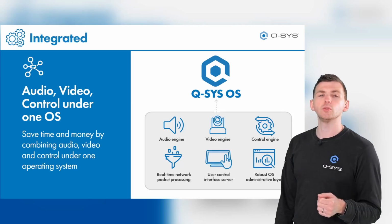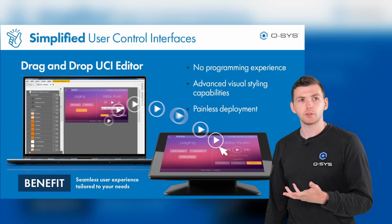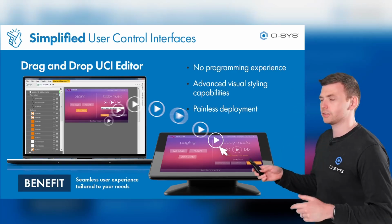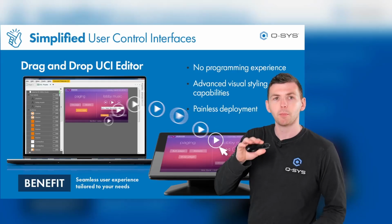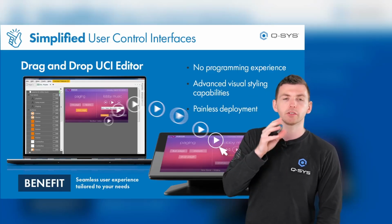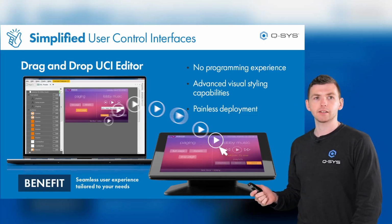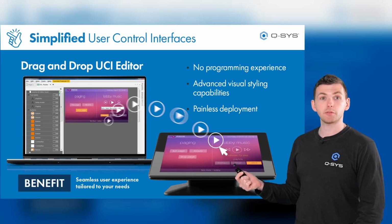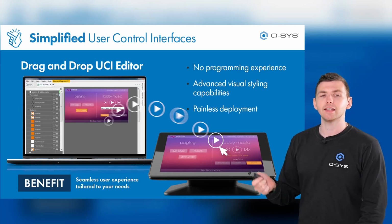So firstly, user control interfaces, okay? Here is the drag and drop UCI editor. And this is what we said about it being simple, right? Within that Q-SYS Designer software, which we saw earlier when we looked at the cameras, we can open up any of those components we saw, take any control from any device, whether it's a software device or a hardware device, and we can drag it onto our touch panel editor, and with no program experience, no coding at all, you can design a very pretty user interface that can do whatever you want,